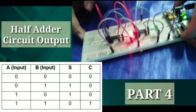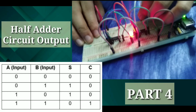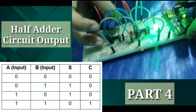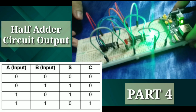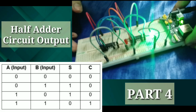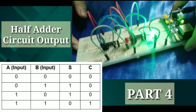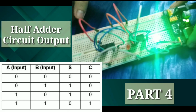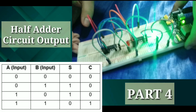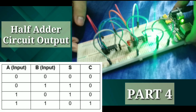And last but not the least, if both input A is 1 and input B is 1, then the output C, or the green LED, turned on. It means that our output is 1 and the output S is 0, meaning the red LED is turned off. So that's our truth table for our half adder circuit.